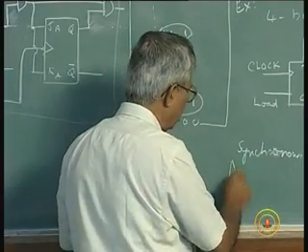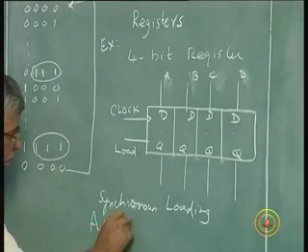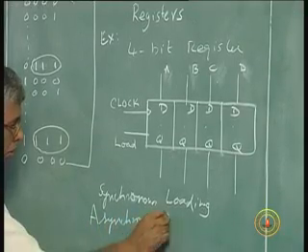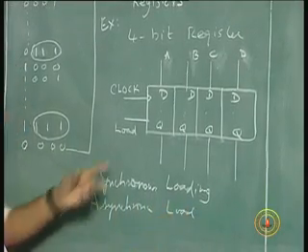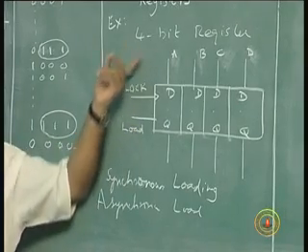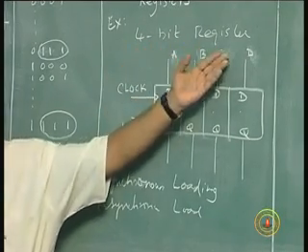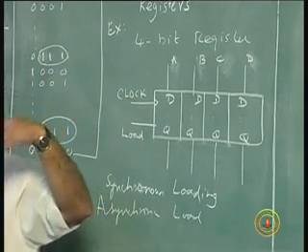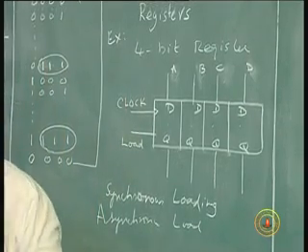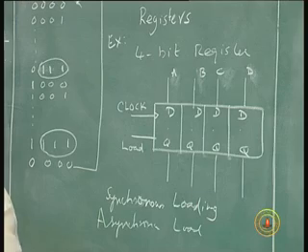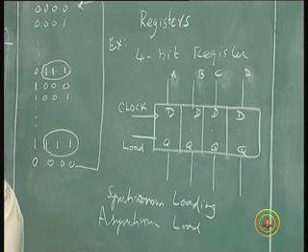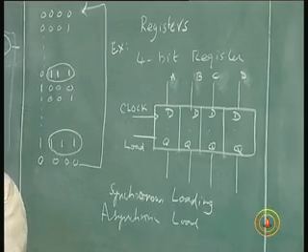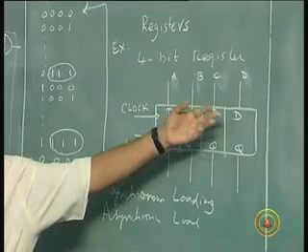Asynchronous means as soon as the load pulse arrives, the data will be stored, whatever the data found here, irrespective of the clock pulse. That is similar to the preset, reset, preset clear conditions we talked about. You can have a choice of synchronous load or asynchronous load. But the advantage is when the load is removed, the stored data is here inside.